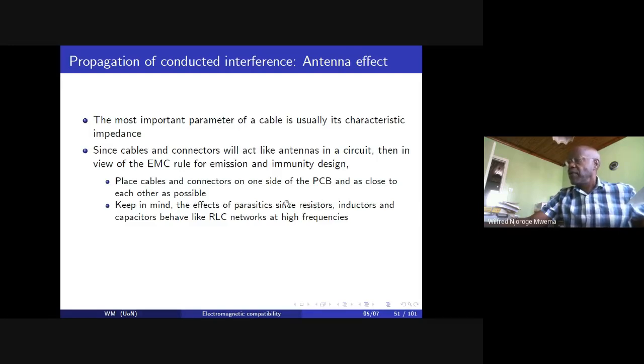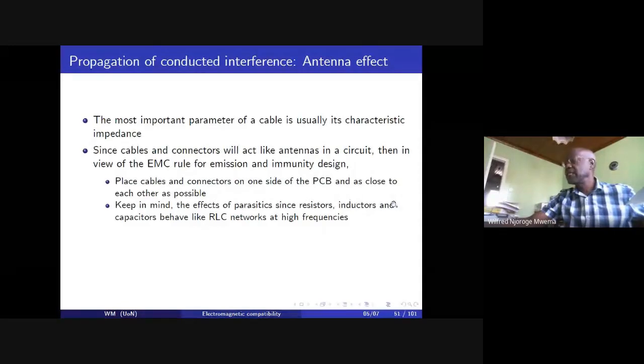Then the resistor itself, which is in the form of a rod, maybe on one side will have the input lead, which will be at a higher potential than the output lead, and therefore the separation of those two is a capacitance over the resistor. Then we have another capacitor between the signal line, the input lead, and the ground potential, and the output lead and the ground potential if it's floating.